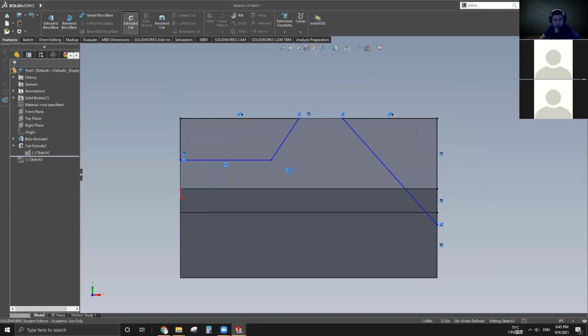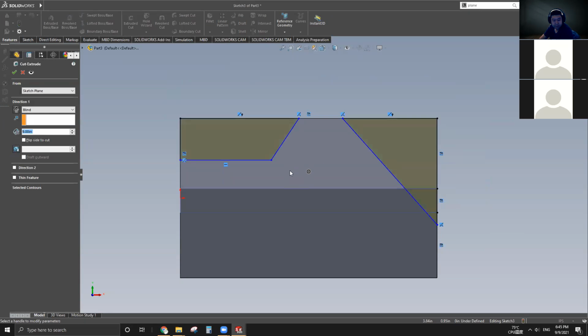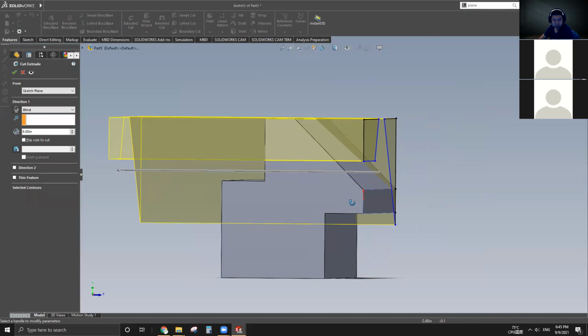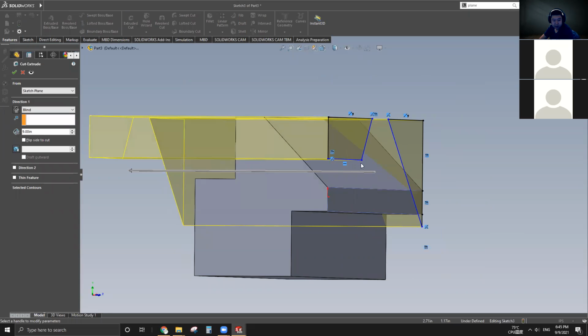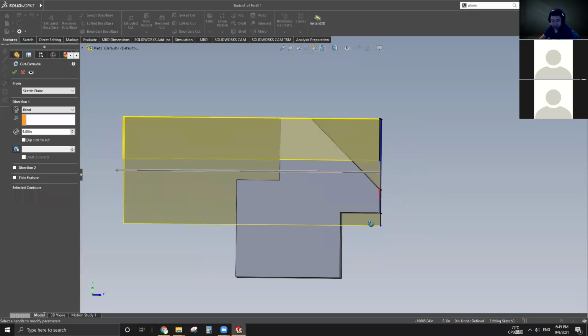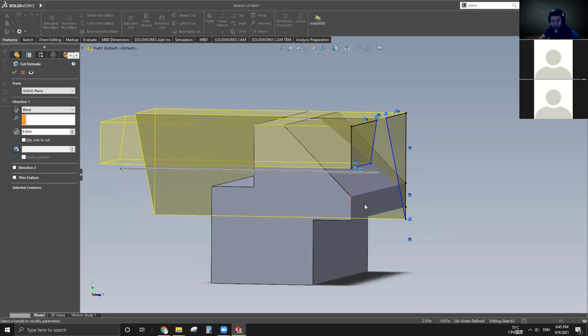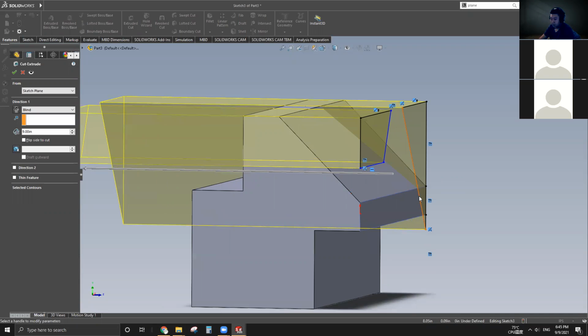And we extrude cut it. So from the preview, you can see the sketch, even though the sketch is not touching any of the model and is on the same plane of the surface we selected, it's fine since we're removing material. So any material along the way will be removed. Same thing happens when adding material.